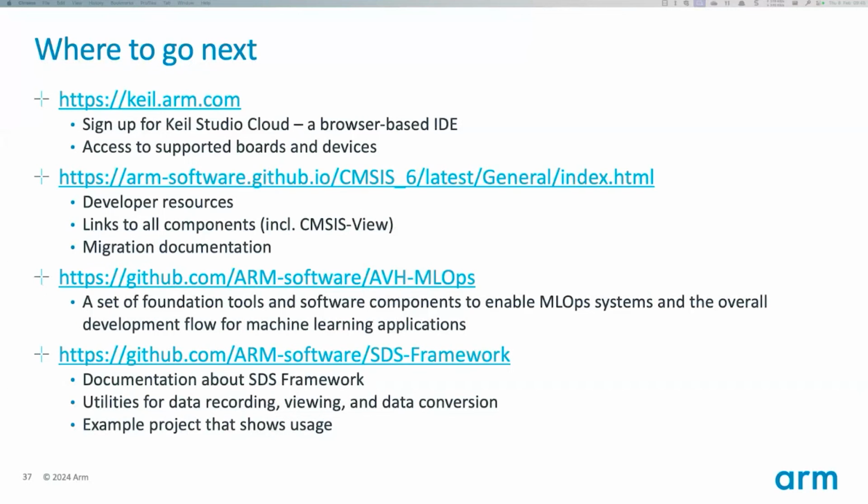Is ARM virtual hardware certified for safety-critical software development, or are there plans to have it certified? The models are not certified for safety-critical software development. We have our ARM compiler for functional safety that is qualified for FuSa. We have a software package that is available for FuSa, our Keil RTX, together with the event recorder technology, and the ARM-specific CMSIS core part is also available for FuSa. The models themselves are not.